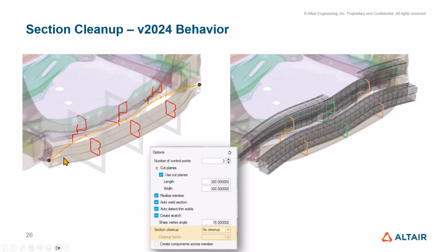Anyway, you can see the raw output. The control points are not in the right location due to the over capture of these areas up here. You end up getting basically this on the right hand side, which is not in the correct location, plus you've got the overspill and the 1D elements on bits that aren't needed, or the section.